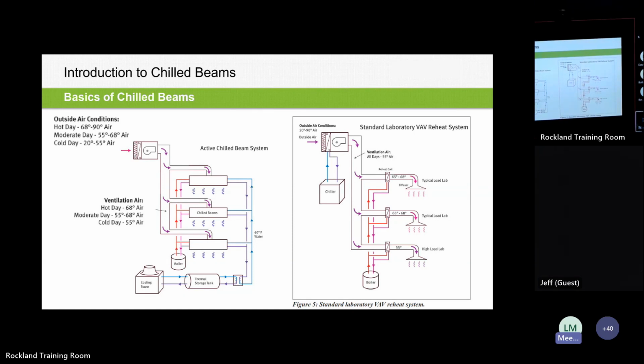With the chilled beam system, you can cool based on the local requirements within the lab space. They can all be different lab heat load requirements, but you can modulate those water valves based on that local load. And there's a number of things that could also come into play, like hood diversity, right? Where you're not designing for every fume hood to be wide open.